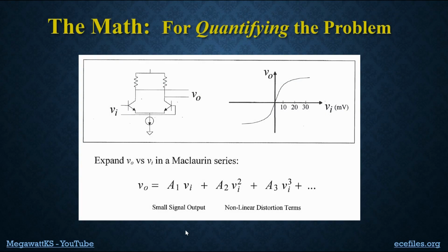So here, finally, is that mathematics. I'm simplifying a little bit by going from that single transistor amplifier to what's called a differential amplifier. And you may know about these, you may not. If you don't, don't worry about it. The point is that you have an amplifier. The output voltage change here is bigger than the input voltage change. And we can see that on this graph. If the slope of the output versus input voltage characteristic is greater than 1, then we have amplification.